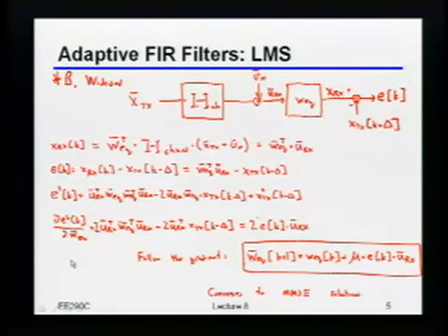So the whole trick with LMS was basically that at the end of the day, if you looked at what it took to minimize the mean squared error, and you just took the derivative of the error, then something nice happens: you can figure out that the direction you need to move in is always essentially the instantaneous error times the instantaneous value at the input of the equalizer.